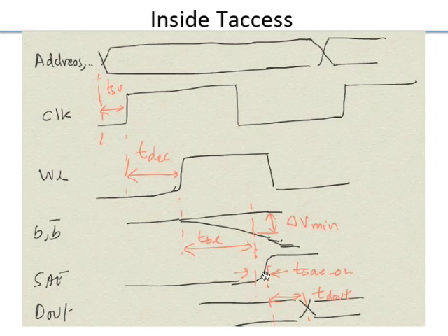Finally, this sense amp enable overhead is something which you can try to reduce, where somehow you perfectly generate the sense amp enable exactly at the right time. Okay, we'll look in the next few slides at how to do that. And then sense amp to data out is again what you have studied before. There is nothing new in terms of optimizations needed to speed it up. There is a certain load the memory has to drive. Sense amp output is pretty much digital, and it has a certain drive strength. So you have to buffer it up and drive. There's not much you can do there.